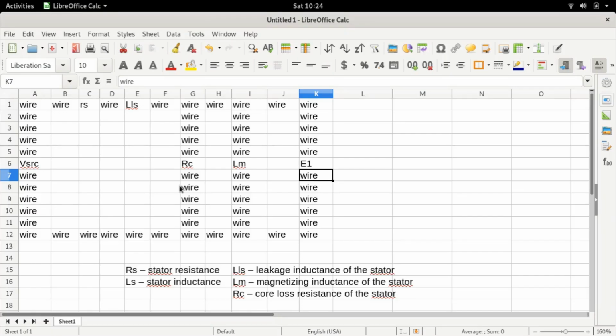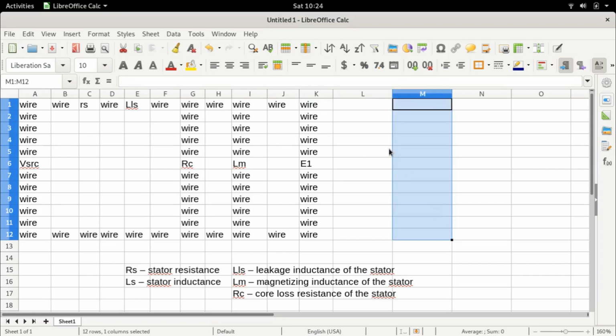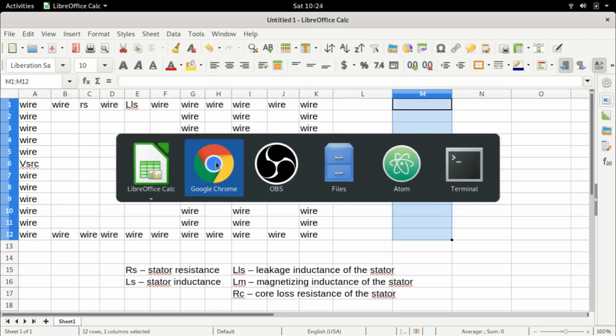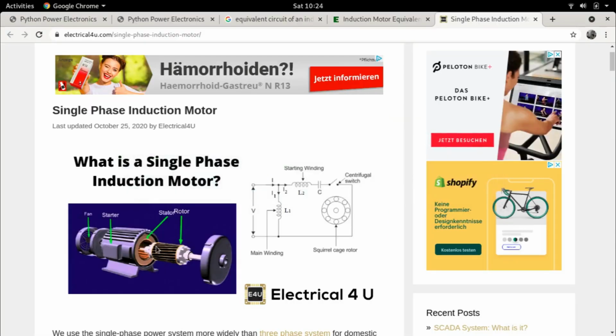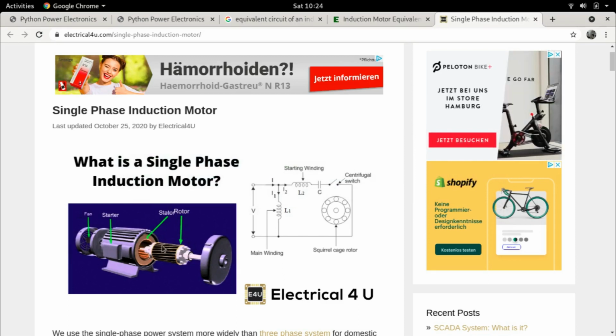So let's go back to our circuit. What that means is I'm going to give a space, because remember, there is no electrical connection. Right? If you come back here and look, there is no electrical connection between the stator and the rotor. This rotor is mounted within this. It is short circuited on both ends. So there is no wire connection between them. The connection is purely magnetic.